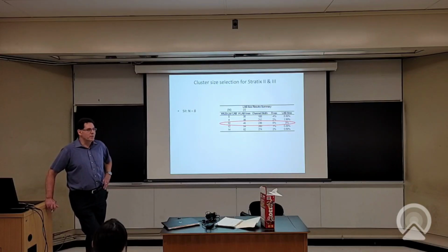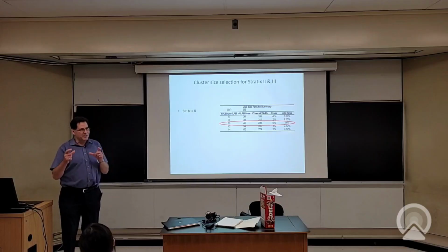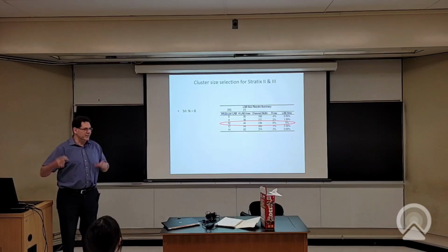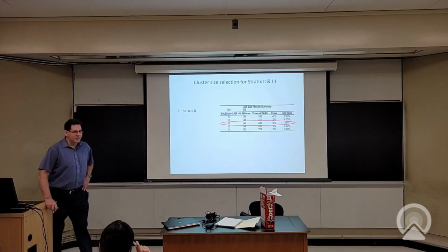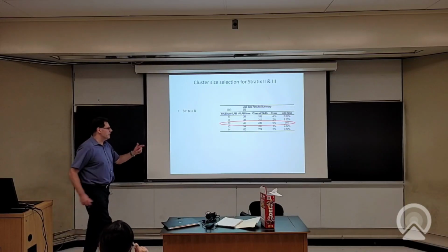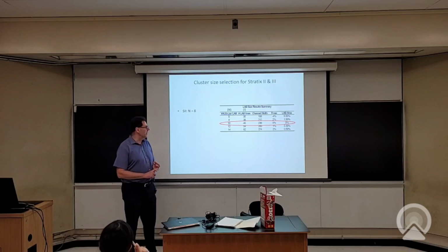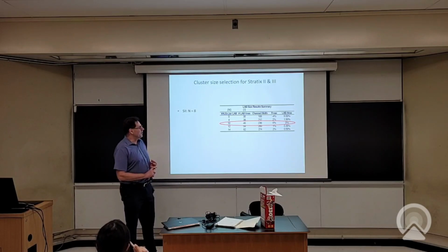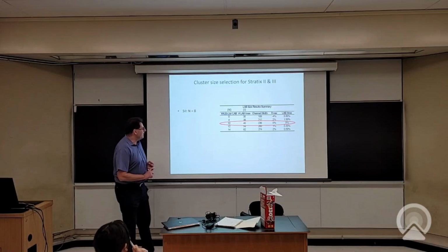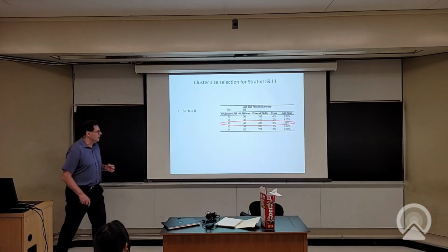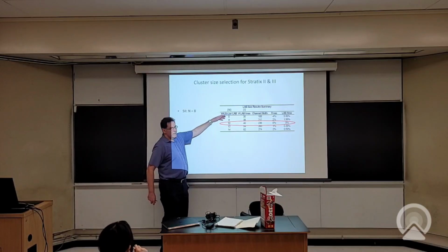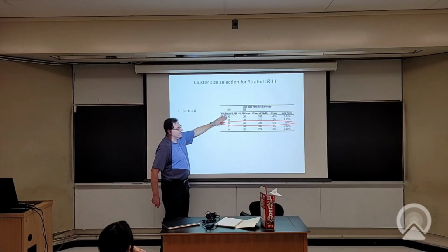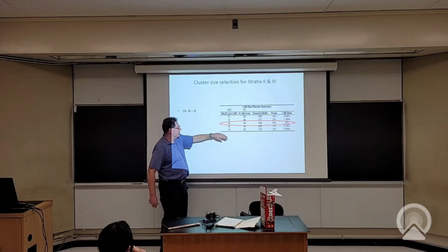There may very well be a better architecture there, but you have to basically think about the routing and the logic simultaneously, right? So, okay, same paper, they have fractional 6-LUTs, this is their design. They now need to decide how big the logic block is. And the paper gives a bunch of results on how many of these, they call them ALMs, which in the paper they inexplicably call ALEs, because that was the engineering term. So they can make 6 of these fractional LUTs, 8, 10, 12, etc.